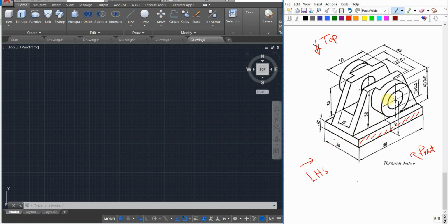Then you just draw, assuming that this cylindrical thing is not there, and even this opening is not there in the beginning. And then I'm just going to draw this entire face, like a complete trapezoidal shape. Then I'm going to extrude it with this distance, which is already given as 30. Do you see the 30? This should be the extrusion of this face, right? Then we can work on the cylindrical thing and the other features. So let us build these base things first, then let us see how we can move on.